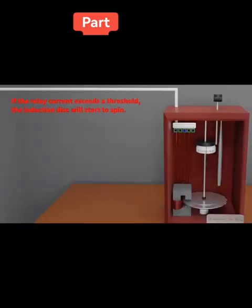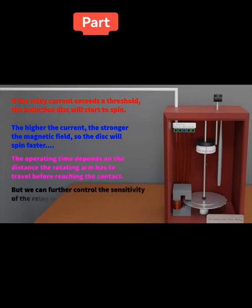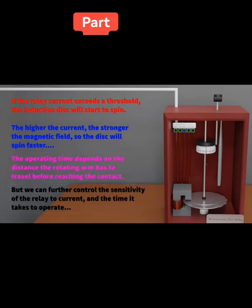And the higher the fault current, the higher the relay current, and the stronger the deflecting force on an induction disc will be. So the relay will operate faster for a higher current. We also note that the operating time depends on the distance the rotating arm needs to travel. And we also know that the sensitivity of a relay to the current can actually be changed. And these two points are important because they allow us to configure the relay to suit a particular value. So this is very important.